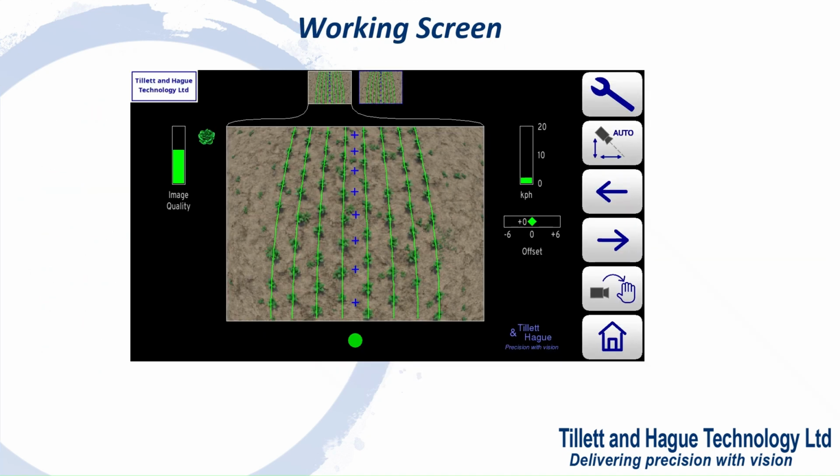This is the working screen. It features a live video image with template and tracking crosses overlaid. A green dot or green chevrons below the image indicate side shift or disteer position. A red chevron with a vertical bar indicates the limit of travel has been reached. This should not be allowed to occur for extended periods.